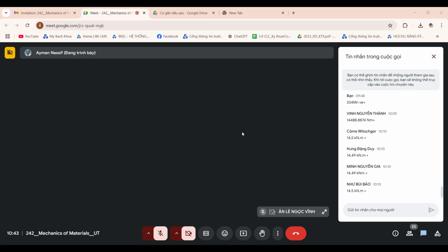Sorry, I ended up moving the image, okay? So we have 1 degree of restraint in the vertical direction, and we can write it like that. We can indicate it by these wheels here, which allow horizontal movement along this plane. So we develop a vertical reaction perpendicular to this plane. This reaction can be up or can be down, actually. Please understand, it looks strange, but the reaction also can be down. If we need the reaction to go down, we need to design the reaction to do just that.